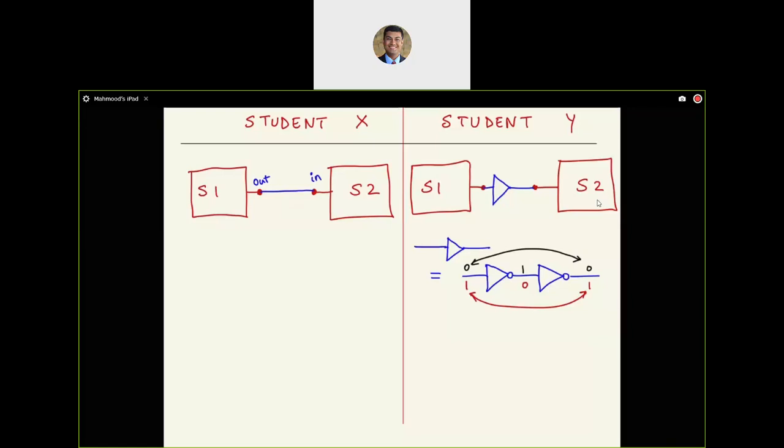Well, one is going to be better than the other. And here's the reason. If the output of stage 1, say, becomes a weak logic level, say over here we have a weak signal, weak 0 or a weak 1, then during this transition, or if you have more things connected to the same output of stage 1, you might not get a strong enough input of that logic level into stage 2. So that's a problem. If it was a strong signal here and these were not there, you'd probably be okay. Strong logic level goes to the next stage.